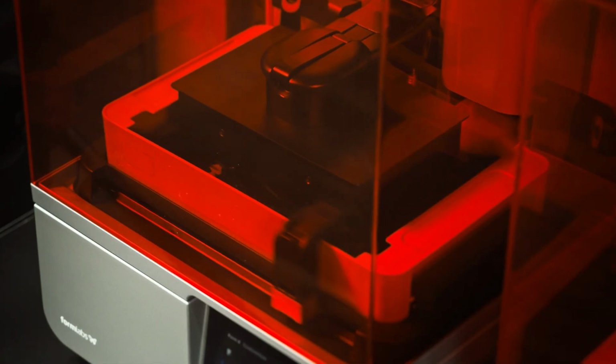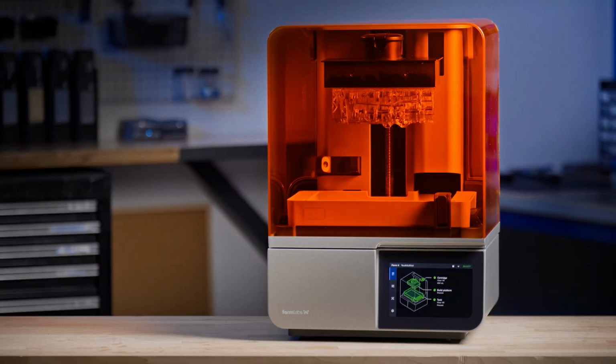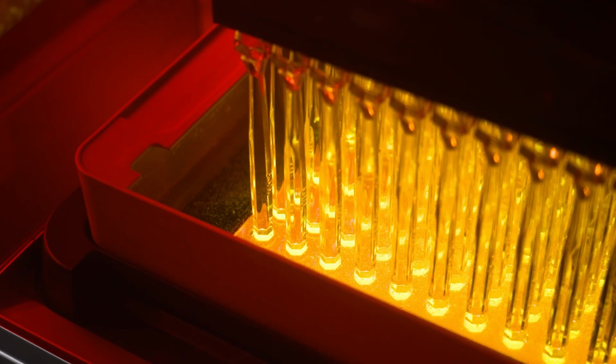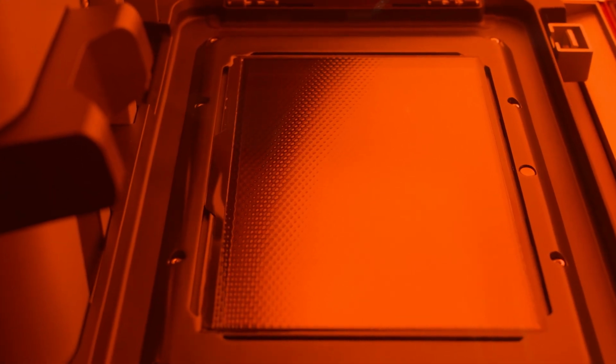If the obstruction is on a stationary surface, a hole may develop directly above that point. If the blockage is on a moving surface, a linear cut may develop instead, following the path of the blockage. On Form 4 and Form 4L generation printers, all of the optical surfaces remain stationary during the print, so a pinhole could be due to debris in the resin tank or on the LPU release texture.